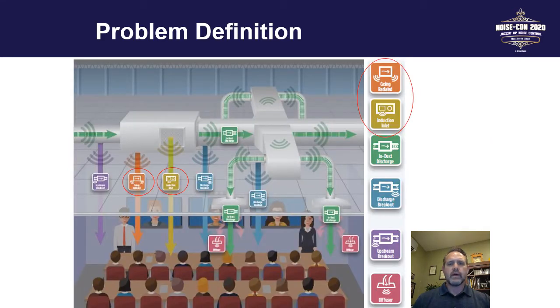Before I get started, I want to define a little bit further what we're talking about when we talk about an air terminal unit. In this case, some examples would be a VAV, a fan-powered VAV, a blower coil, a water source heat pump, a fan coil, things of that nature would fall into this classification and category. And as you look at an air terminal unit, there's a variety of noise transmission paths that can be present, shown in this illustration here.